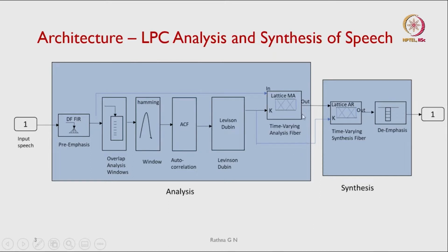Here we will be doing both analysis, which is this equation, and synthesis, which is this part. We will be incorporating both of them and then see the demo. Otherwise, in the normal case this would become a channel and you would be sending it out, and then at the synthesis part, that is the receiving part, we have to de-predict, that is we have to run the lattice filter, which is a time varying moving average filter.